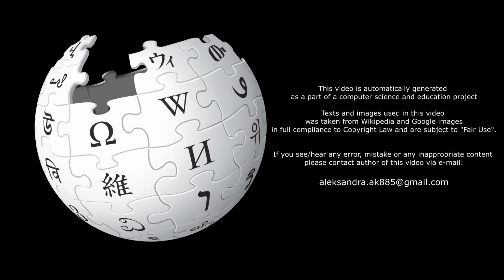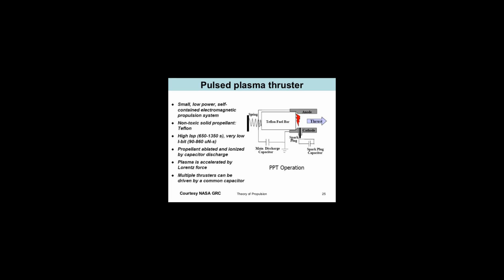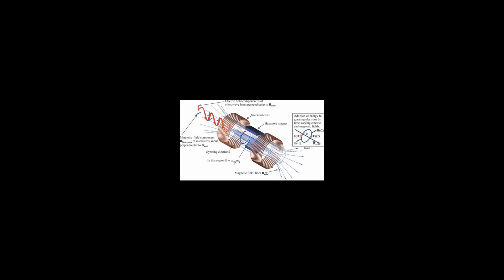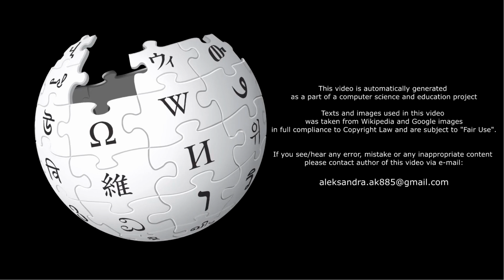The exhaust velocity of a PPT is of the order of tens of kilometers per second, while conventional chemical propulsion generates thermal velocities in the range of 2 to 4.5 kilometers per second. Due to this lower thermal velocity, chemical propulsion units become exponentially less effective at higher vehicle velocities, necessitating the use of electric spacecraft propulsion such as PPTs.